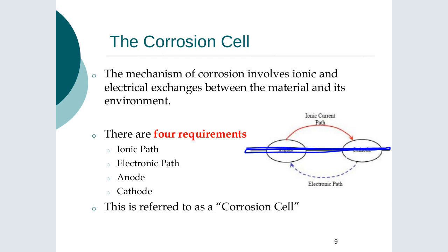But very often what can happen is that you get damage to the surface. So we get some sort of a dent in it, the corrosion product is removed, or the paint is stripped or damaged in some capacity. And our anode is extremely small, but if we have a large cathode somewhere else, it will drive a very, very high current through this and can lead to an accelerated rate of attack way beyond what you originally envisaged. And again, bear in mind that your thoughts are, well, now I've painted it, surely the surface is protected.